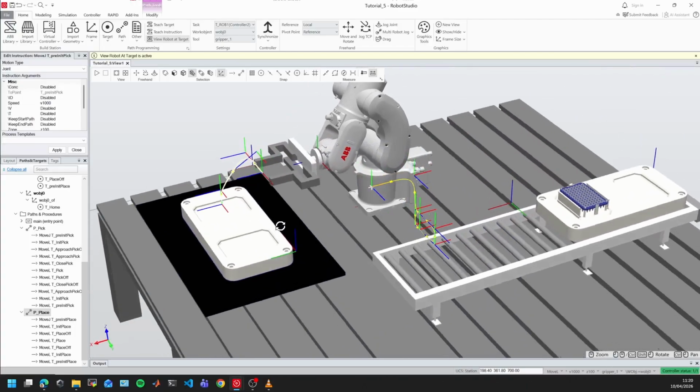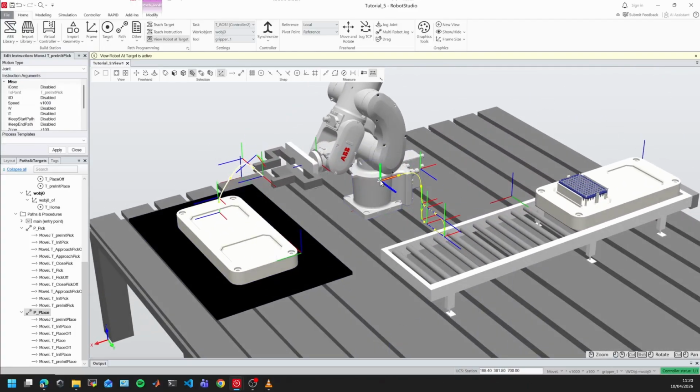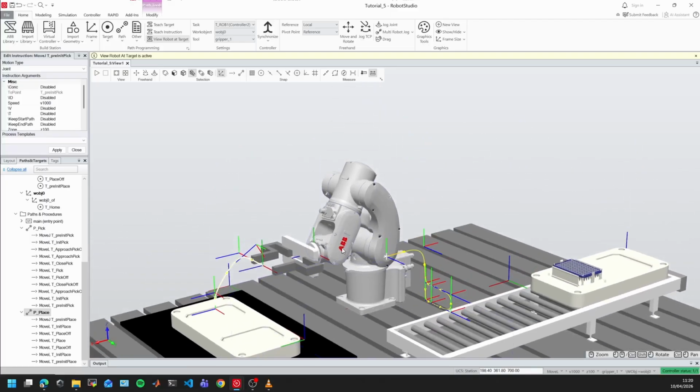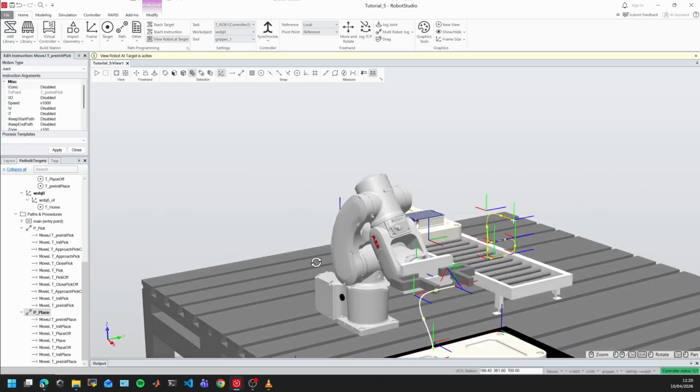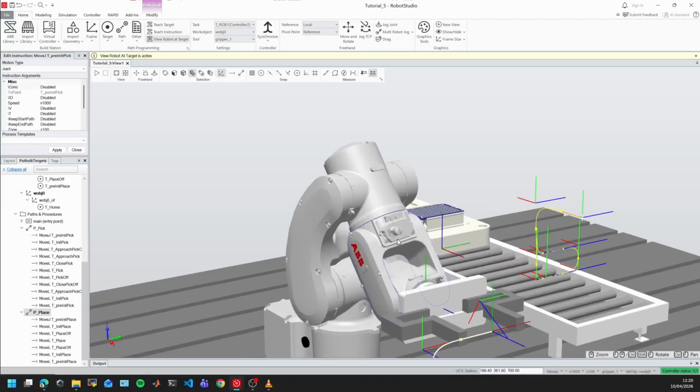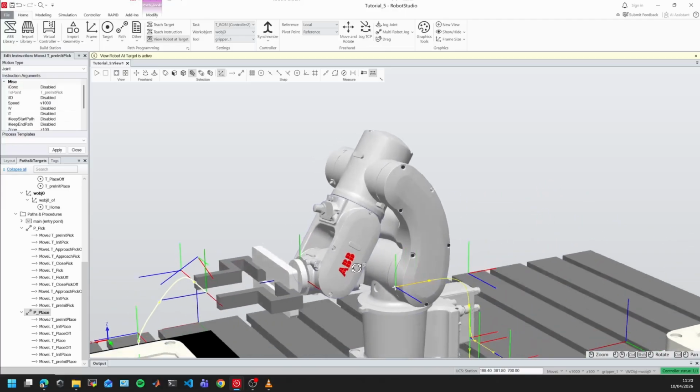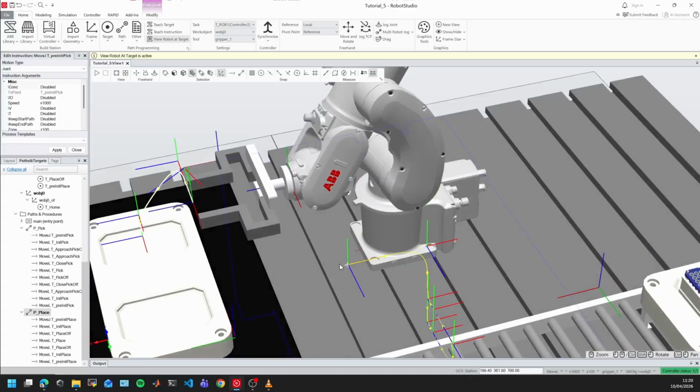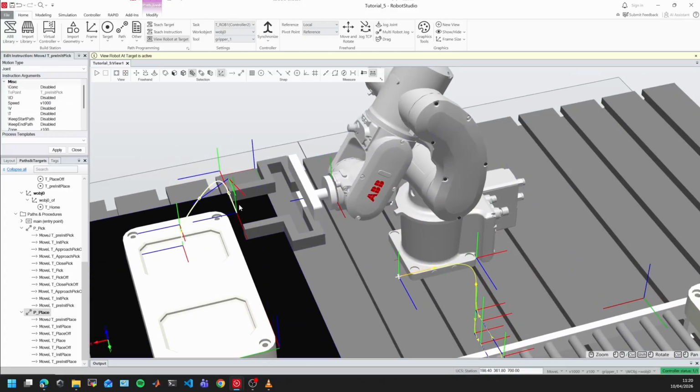So, things to remember always: the configuration at each one of the targets. We have to configure how our robot is, the joints of our robot, because there can be multiple configurations for each one of the targets. One of the tricks: look for some features in the robot and try to keep those features without large movements. So avoid making large movements.